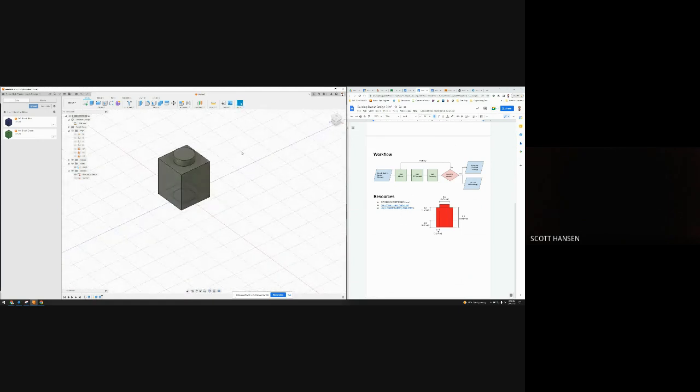You can also edit the appearance and the material used in this block. And so when I created my extrude, I now have a 3D body. Let me right click this body. Let me go ahead and rename that 1x1 block. All right, let me right click that. You'll see how I have two options, one for changing the physical material and one for changing the appearance. Let's go ahead and set the physical material for this block. The physical material menu should pop up.